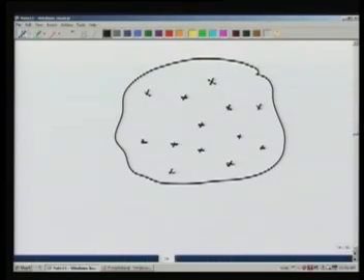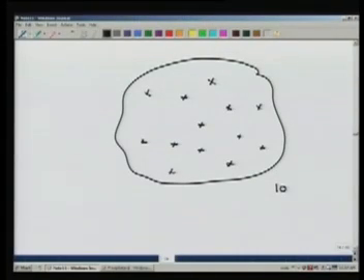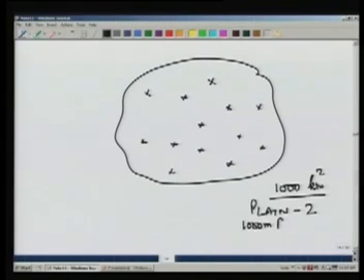So there are some guidelines which tell you in how much area how many gauges should be used. For example, in India, the guidelines are for 1000 kilometer square area, if we have plain area, 2 rain gauges are sufficient. If you have moderate elevation, for example 1000 meters elevation, then you may need 3 to 4 rain gauges in 1000 kilometer square area, because the spatial variation of rain is likely to be more than in the plains. And for hilly areas, typically we need to use 8 rain gauges over 1000 kilometer square area. So these guidelines should be followed whenever we are designing a rain gauge network.